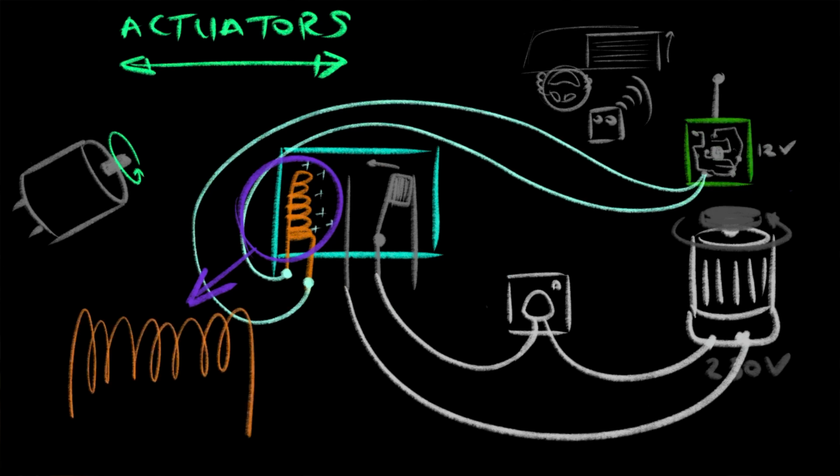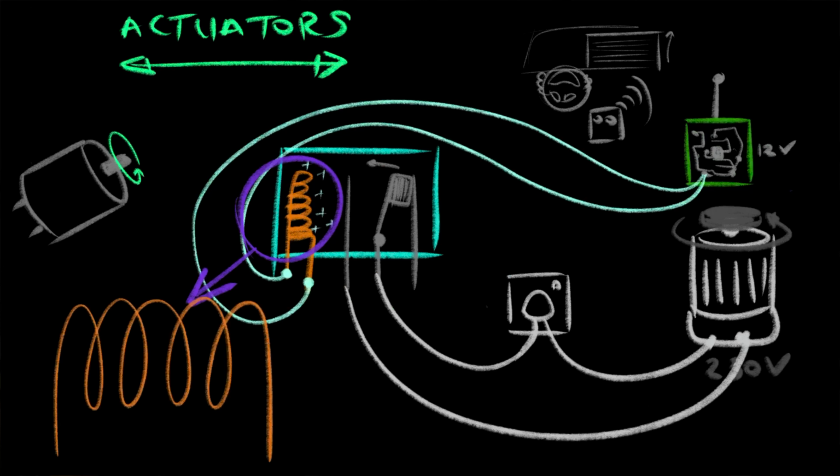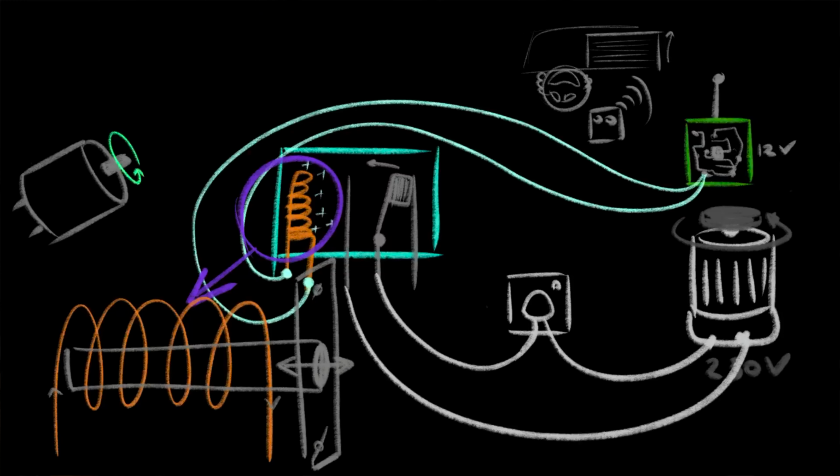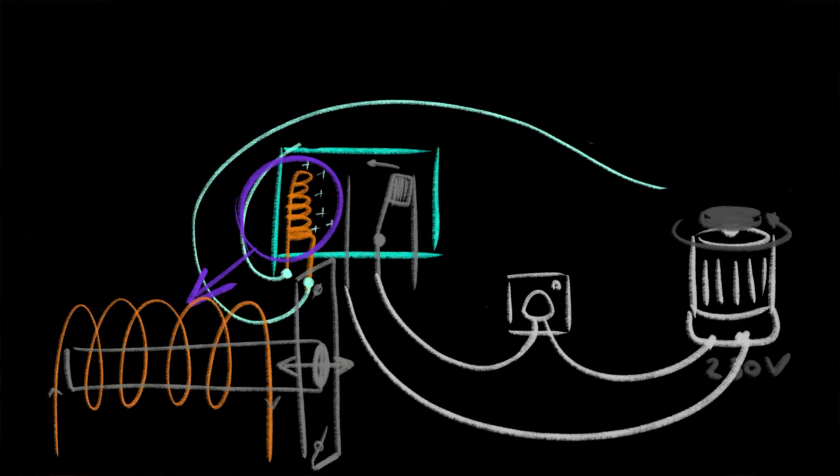Speaking of coils, a solenoid is another use of a coil, where a metal bar is placed in the middle of the coil and made to move backwards and forwards by changing the polarity of the coil. Solenoids are frequently used in electric door locks where the lock can be opened remotely, for example from an intercom screen 5 floors up in a block of apartments.